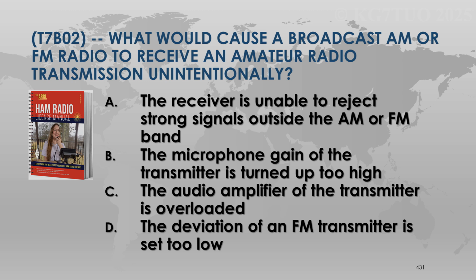Okay, can we throw out B? First, can we throw out B? Microphone gain. It's turned up too high? Yeah. Probably turn that one out, right? The deviation of an FM transmitter is set too low.